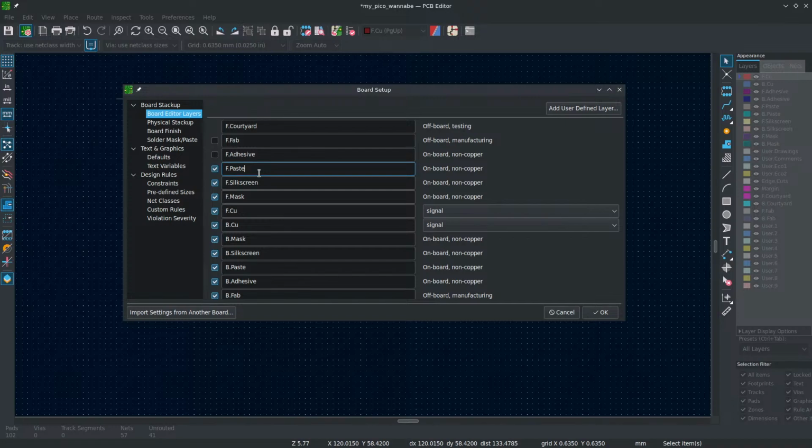So instead of feeding solder on, they put paste down on everything. That's the layer for specifying that. It's automatic in KiCad, by the way. You don't need to specify the paste layer unless you're doing something special, so you don't have to worry about it usually. I'm going to turn it off to keep it clean.